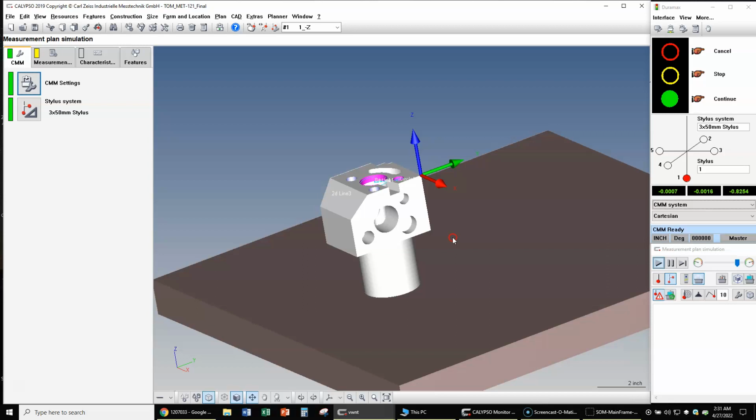So that's the beauty about being able to do this right on the machine. You don't even have to position the CAD model. In fact, you do not want to position the CAD model. Your manual alignment will position it. So only orient it, but don't position it. Only orient it if you have to. All you'll have to do is spin it one way or another. You'll either rotate about X, about Y, about Z, or some combination, but you'll do no linear movements at all. That is an important point. I would put that in your notes.